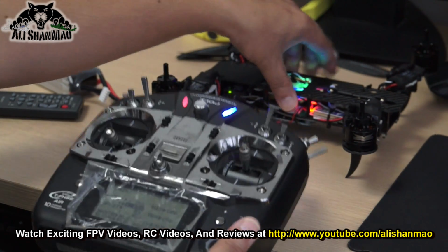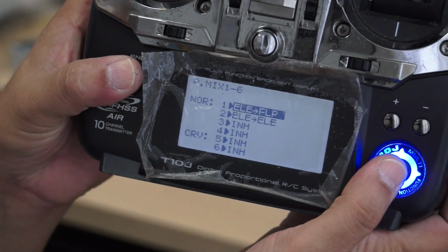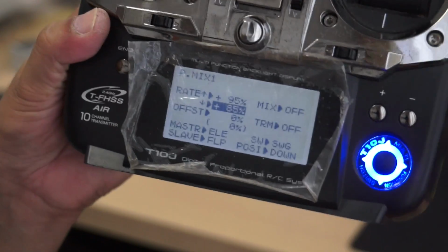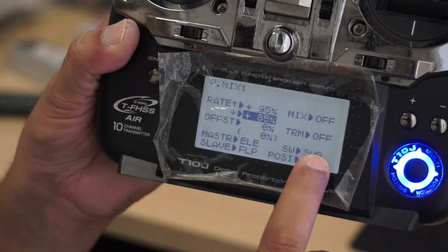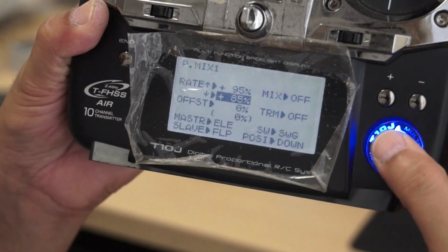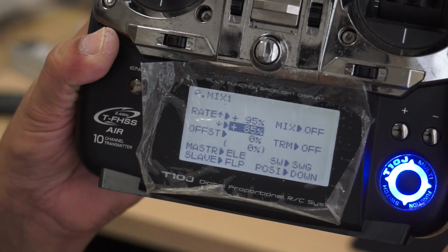Okay, so let's review one more time. You're going to make the first mix, which is elevator to flaps or elevator to the channel where your servo is connected. So elevator to flap, switch G to activate, to turn it on and off. As you can see, on, off. Let me put the lights on and off. You can see mixing is turning on and off.